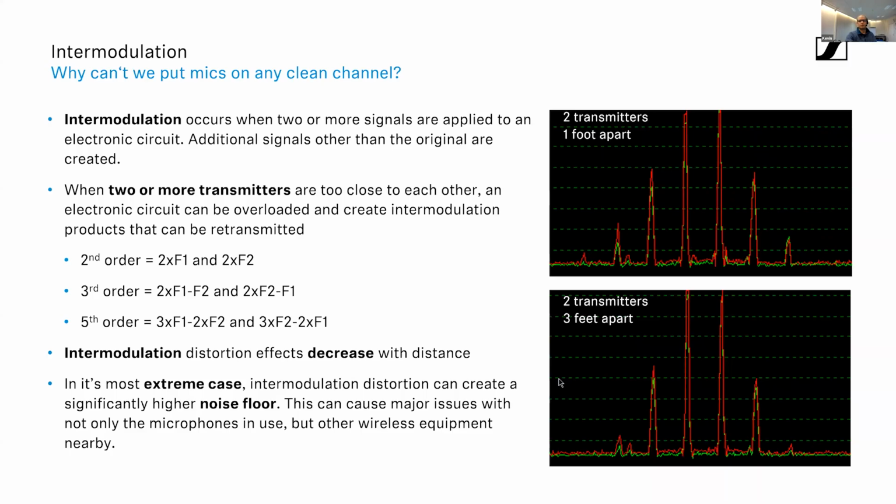Right, and so now that we know a little bit about how all systems work, and again, this is not specific to analog versus digital systems. This is about systems that can produce intermodulation and systems that do not produce intermodulation, right? So pretty much every system on the market, with a few exceptions, which we'll talk about here in a second, produces intermodulation, and now you have to avoid it. You need to either stick with banks and channels, or you need to do complex coordination to figure out where this stuff is.